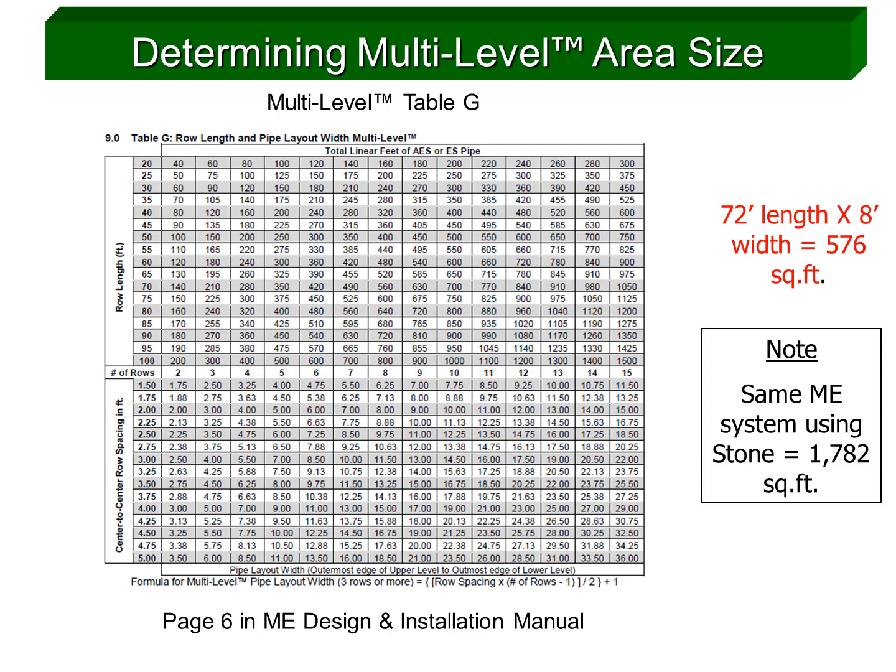Now let's find our field's information. In our example, we're using a pipe row length of 70 feet. Finding that in the far left column, we move right until we encounter at least 420 feet of pipe, at which point we move down that column and see that 6 rows will be required at 70 feet in length to satisfy our minimum 420 foot requirement.